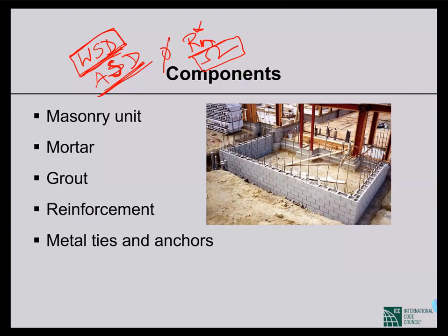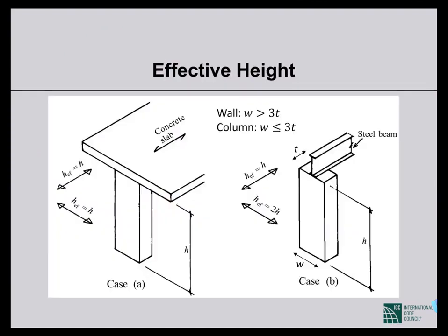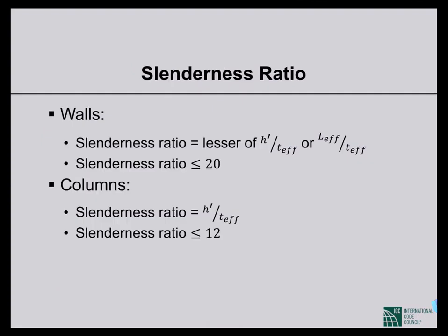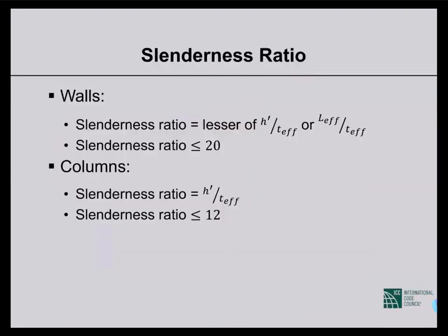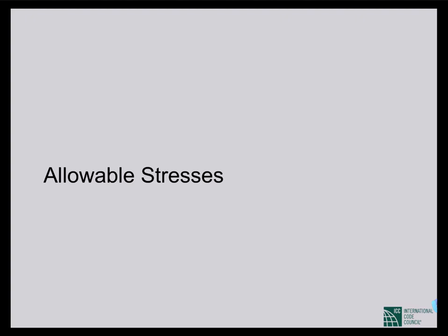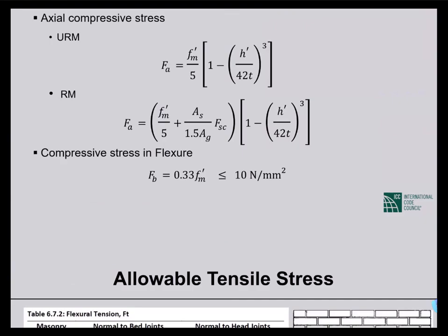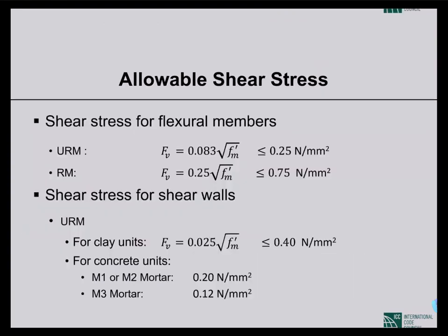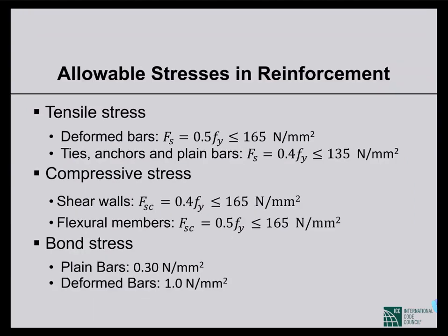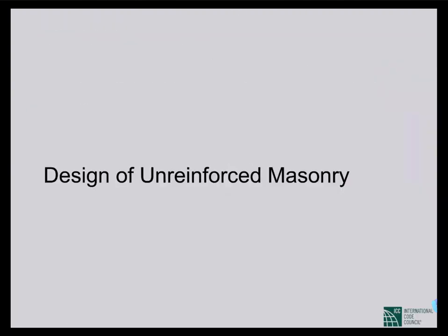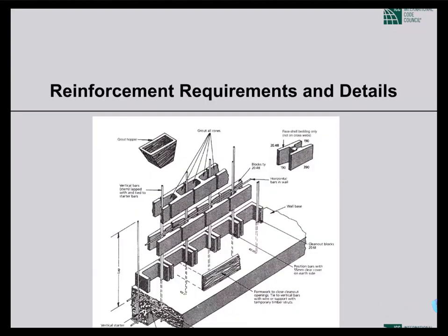Maximum number of story or maximum height of a load-bearing wall masonry building, that is given. Both maximum number of story and maximum height are given. I showed a table, I'll show again. So stiffening, like where there is mention of cross walls, stiffening walls, and that was in basic design requirements, right?